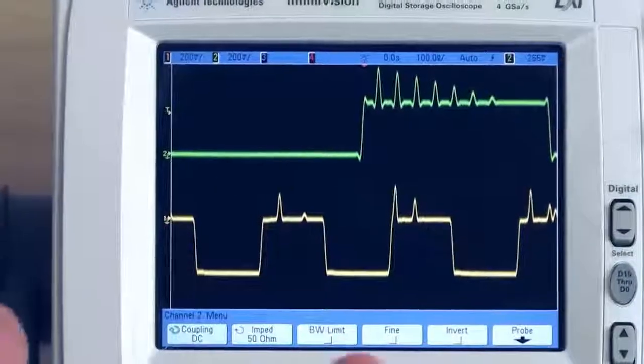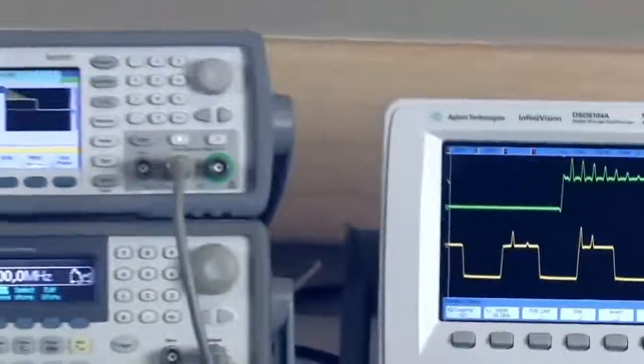So to wrap this, the Trueform generator is capable of generating and reproducing accurately your waveform at any frequency. The DDS generators begin to suffer from not only missing points, but sometimes also jitter on the waveform,